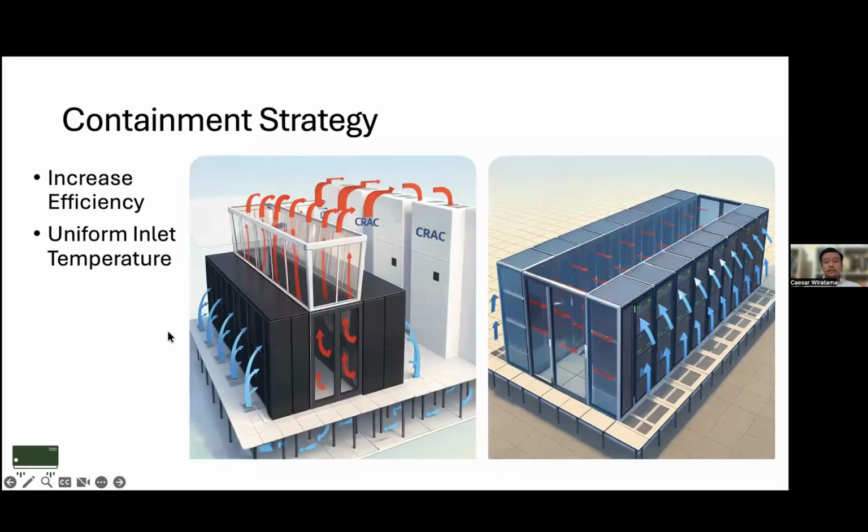Okay, the one thing that we can do in order to manage the airflow is use containment. So basically we add some walls to make the flow directed the way we want. Let's say we put some airflow duct system here, or maybe enclose right here to maximize the mass flow rate and prevent the recirculating problem.